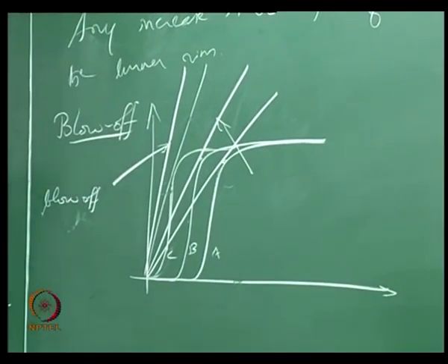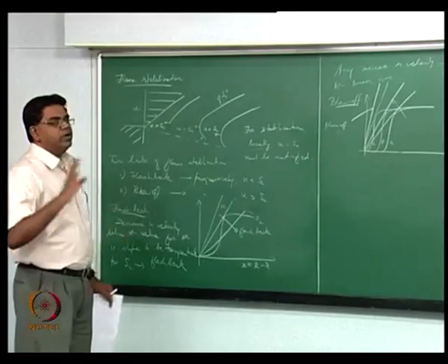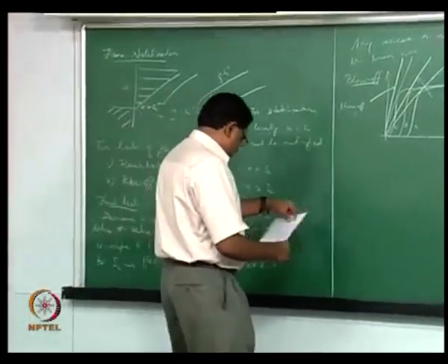So effectively the flame speed, because of these two mechanisms of heat loss and dilution, they combine together to adjust in order to match the flow speed locally as it is being increased over a fairly wide range, but not beyond a point, right, and that's when you're going to have a blow off.